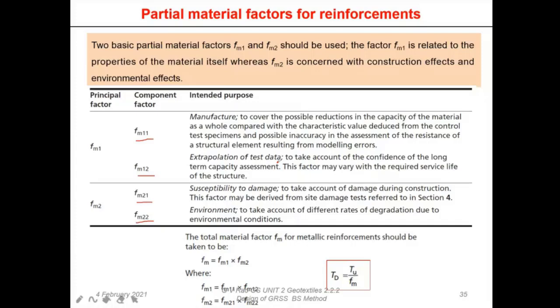And so what we are probably going to do is in log cycles: 1 hour to 10 hours, 10 hours to 100 hours, 100 hours to 1000 hours. So we may do up to say 1000 hours or 10,000 hours and extend it beyond, for years, basically. So the extension is extrapolation of test data, and we have no test data to verify it also. And that too we are going to do by the short-term method of changing temperature itself, not really. So all these things are going to cause extrapolation of test data.